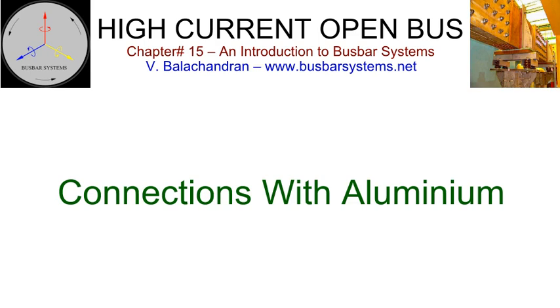It is necessary to have a facility for bypassing a cell when it is taken out for maintenance or rectification or replacement. This will ensure that the remaining cells are in operation while a bypass cell is being attended to. After the cell is made ready, the bypassing is removed and the cell is put back into operation. In the case of an aluminium extraction plant, carbon anode replacement is a part of the process as carbon is a consumable. Therefore, each cell has to be periodically bypassed and put back into operation after the anode replacement. The connections and disconnections are done using cranes and mechanical contraptions.